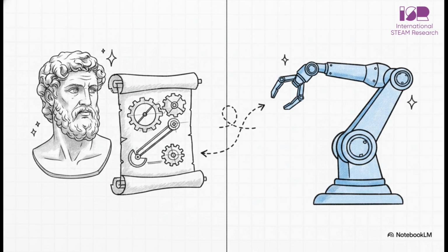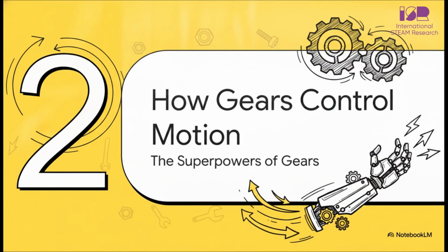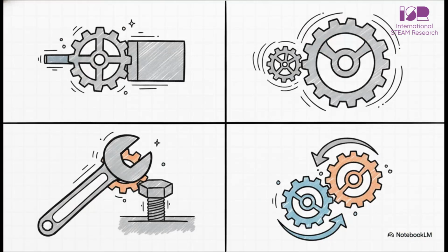So the crucial point is understanding the trade-off that's happening here. By utilizing gears, engineers can choose to sacrifice the high speed of a motor to gain extreme precision. That's called speed reduction. This is absolutely perfect for a robot arm that needs to move very, very slowly and exactly into place. Or they can trade speed to amplify torque. That's what gives a robot gripper the raw, unyielding strength to grip an object firmly without dropping it. You're always trading speed for strength or speed for precision.